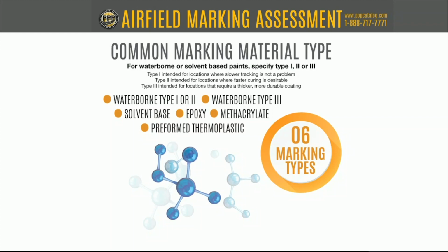But that longer wear, I think it's the Texas Department of Transportation, their pavement marking guide says the durability of a paint is directly related to the thickness of the coating, and that's somewhat true. So if you have a thicker line, it's going to last longer. Well, that'd be a thicker line, not necessarily a thicker paint.